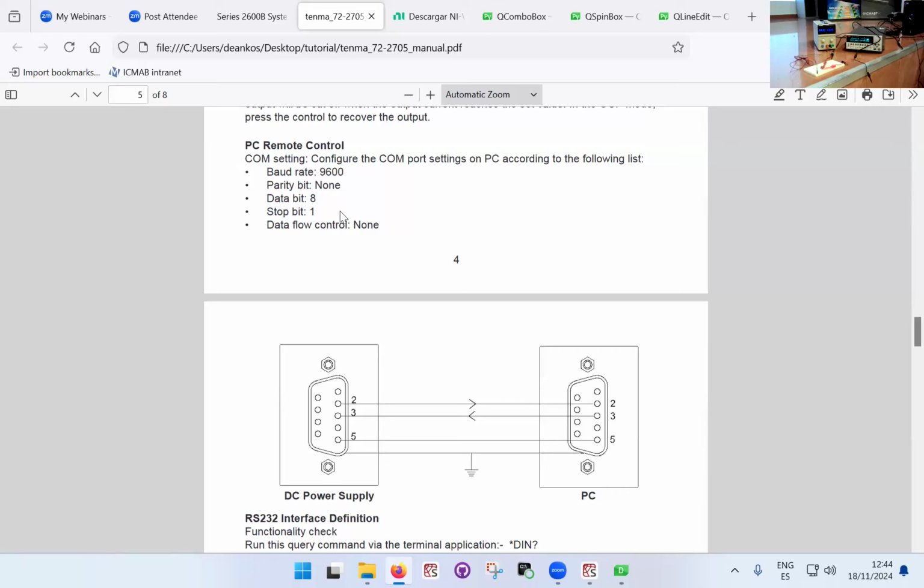In fact, now let's have a look at a few settings. These are typical settings that a serial instrument is going to give you. If you buy an instrument that's communicating through serial, it will generally have a short description of some settings that you're supposed to use when communicating with this instrument using a computer. One of the things is the baud rate.